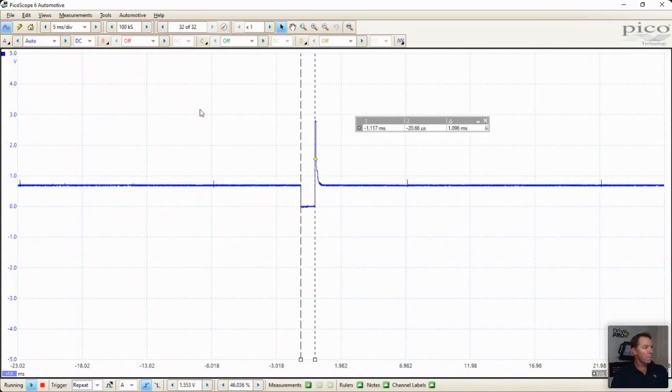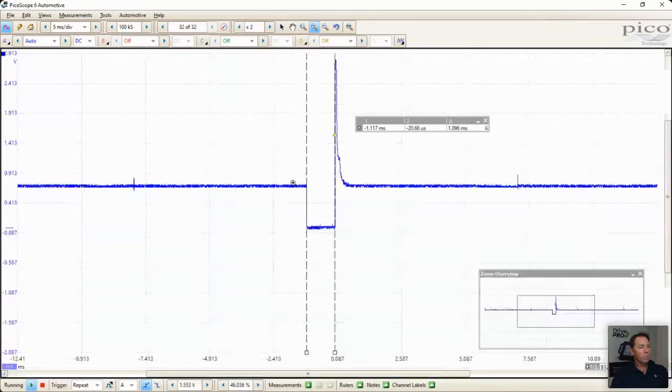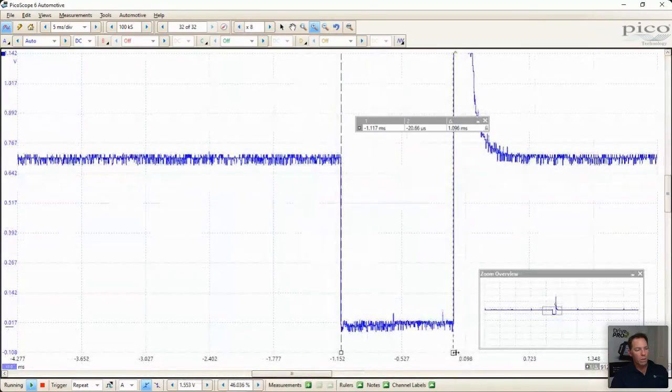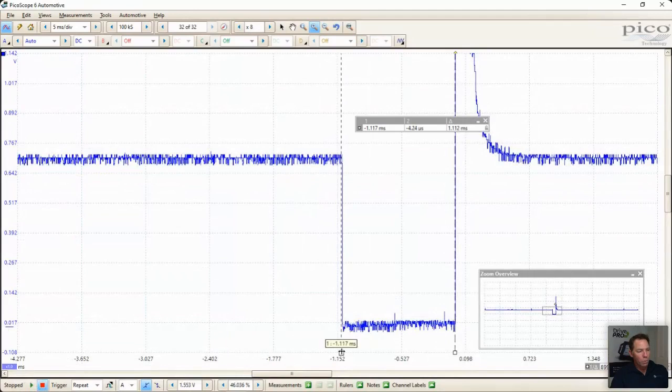Now, on this value here, on this demonstration we've got going at the moment, we can actually see our delta is around 1 millisecond, nearly 2 milliseconds, just based on that. Now we can get really flash, we can zoom in, we can adjust that a little bit, fine tune our ruler to get it absolutely right. We can pause the pattern, we can move that ruler a little bit more to be 100% accurate. But really, what's a couple of microseconds among friends? And there you go, 1.1 milliseconds. As far as injectors go, this is all right looking at 1.